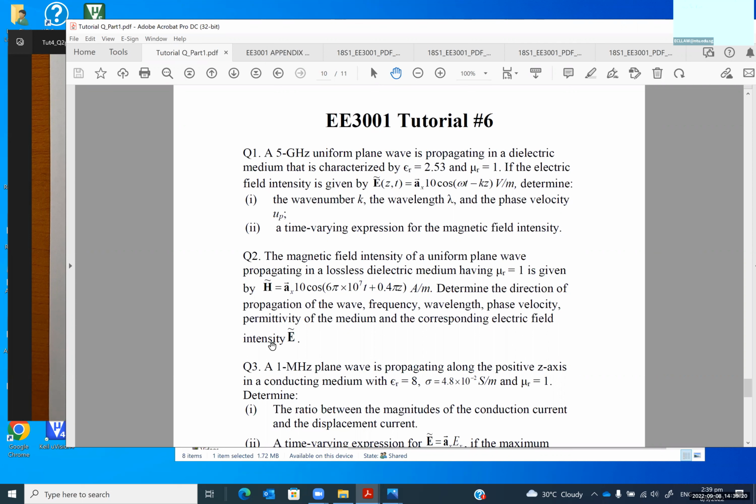If my signal travels from the transmitter to my receiving point, the phase changes as it travels. If I have a second path that hits, say, the ground and goes up, there's a path length difference, which results in two vectors. These two vectors can be in phase if the path length difference is exactly one wavelength. They can be out of phase if it's half a wavelength. So depending on this path length difference, the signal can go up and down.